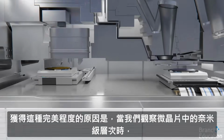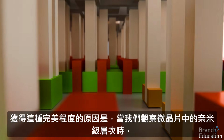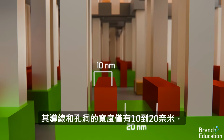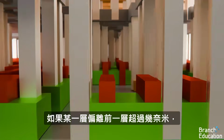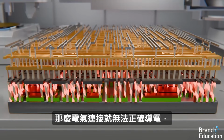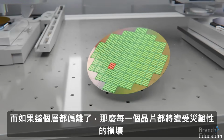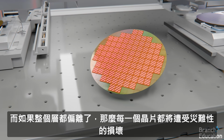The reason for acquiring this level of perfection is that when we look at the nanoscopic layers of the microchip, which has wires and holes that are only 10 to 20 nanometers wide, if one layer is more than a couple nanometers off the previous layer, then the electrical connections won't conduct electricity correctly. And if an entire layer is off, then every single chip will be catastrophically destroyed.